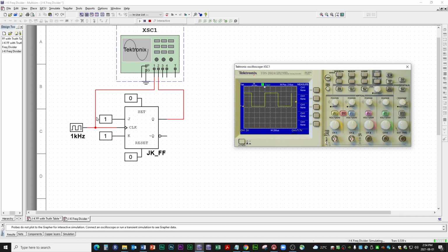Of course, we still have the same signal here, right? Let's make it a tiny bit smaller on the display so we could fit other signals here. And position a little bit up. And I'm going to position that in between those division lines, so on the computer monitor you can actually see that. I know you can barely see it probably. So here we can see the signal, all right? And here's our ground reference, here's our trigger level. Now, let's see what's happening on channel 2, because we have that connected to the Q, all right?